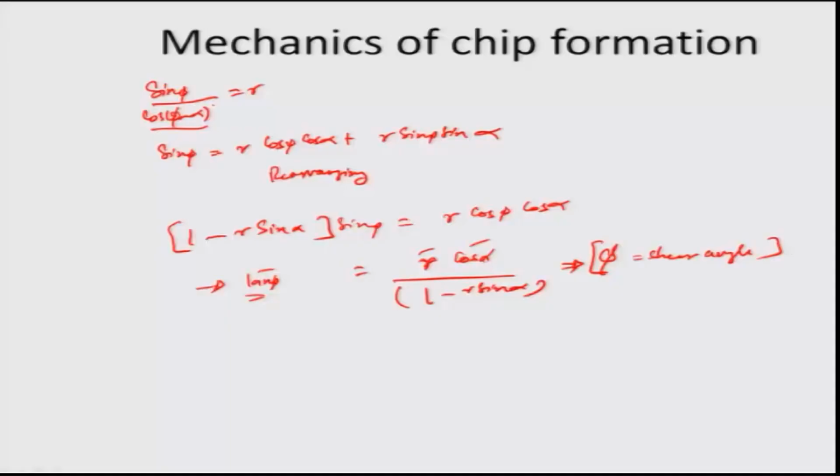So having said that, now we want to just further take one geometrical estimate of what is going to be the shear strain which is involved in this chipping process. So for that, let us actually just draw this chipping process again. Let us say this is the chipping action which is happening, and owing to that there is a shear angle which has been formulated. Okay, let this angle phi be there with respect to the workpiece surface, and we have the extension of the workpiece surface.